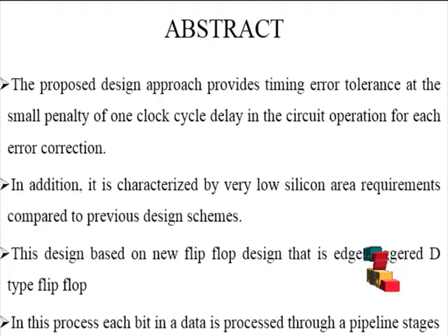Generally, VLSI technology is used to optimize any type of digital architecture, because this type of optimization process is mainly used to enhance various applications. The proposed design approach provides timing error tolerance at the small penalty of one clock cycle delay. In the circuit operation, for each error correction, the main objective is to develop a low-cost multiple timing error detection and correction technique, which is based on a new flip-flop design. In addition, it is characterized by very low silicon area requirements compared to previous design schemes.